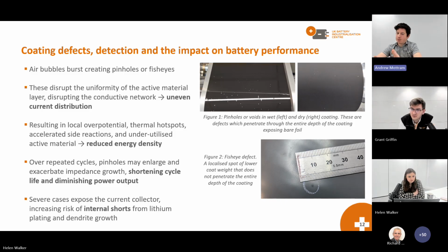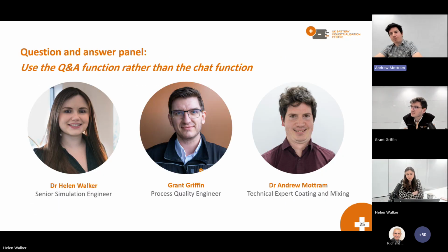The only thing that came to mind is that the size of the defect, the air bubble, can also be linked to the size of any filters that pass through, and the size of the filters relative to the size of the wet film thickness can also be a sign of how the defect manifests on the coating itself. Because we tend to use 50 to 75 micron filters, often the defects tend to be in that ballpark range.